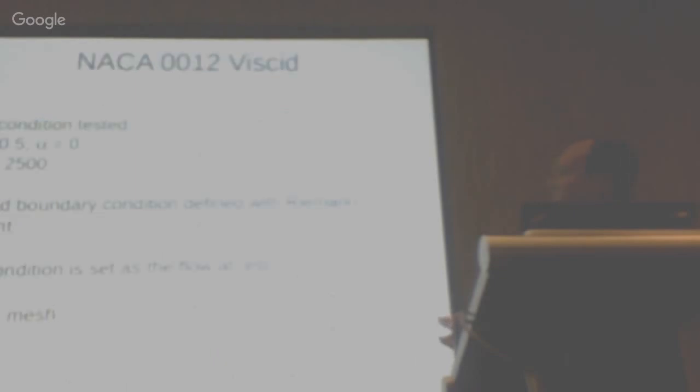This case here is a shorter Mach number of 0.5 and Reynolds 2500. It's a much coarser mesh, but the intent was to see a quadratic mesh resolution. Also, we're using the same algorithm now, the implicit GMRES solver, but with a CFL restriction of 0.8. That was as high as we could go. And this again looks wrong to me, but we're investigating this problem now. Eventually, it reaches convergence or machine zero, but the rate is taking way too long.